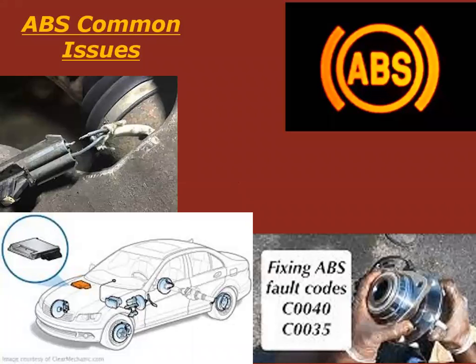So, common issues with an ABS system. Let's talk about that and how you are going to fix them. A customer brings you a car, and it's got the ABS light on. What are you thinking? What are you going to do? Well, the first thing is I would plug in a scan tool and talk to that computer, the BCM, body control module, and see what's going on.